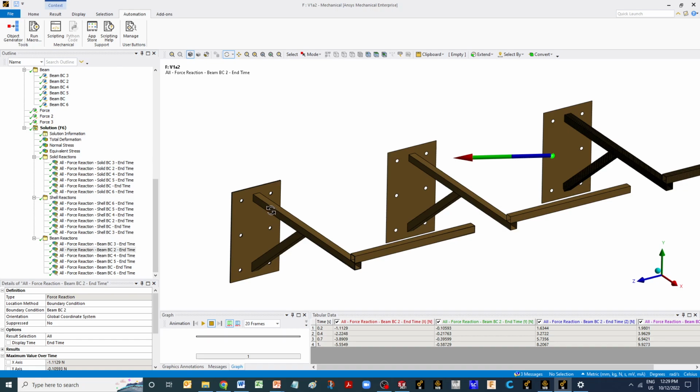And usually in an actual structure, failure happens at the joints. If it's bolted joints, we lose preload. If it is welded joints, we fail due to weld fatigue. And if it is a bonded joint, we usually get peeling and normal to surface failure. So I will have a lot more to talk about. We can go into more details on how the joints are designed in subsequent videos.